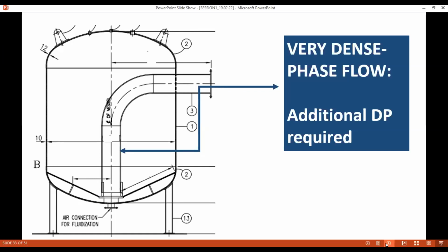So the pressure drop across the blow tank in a top discharge blow tank is always more. Once again, this has to be calculated, and you have to make a similar DP drop in the conveying air line, and accordingly the orifice has to be selected properly. So these are small things. The orifice, you see, is a small thing, but it is controlling the operation of your plant. You can't ignore that.